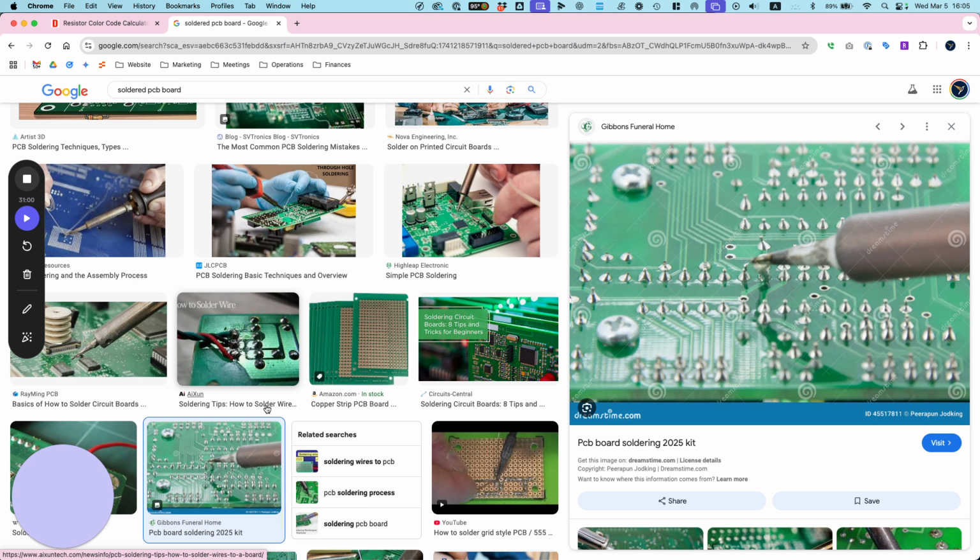I do want to go over a couple slides though, because we kind of flipped the order. I'm glad we did more soldering today, but I want to show more stuff because I'm trying to show you guys how to build your own drone, right? That was one of the requests. So I need to go over some more concepts. This type of board, the one that are not connected, sometimes you're going to have to bridge it eventually at certain points. So if you look here, we have a diode, and then we have a resistor. They're separated by 2 holes.